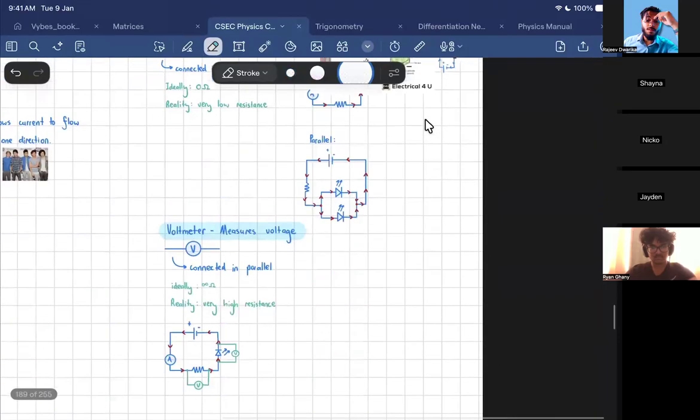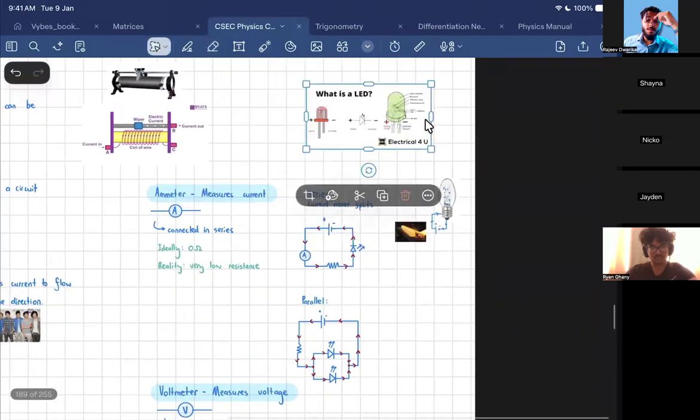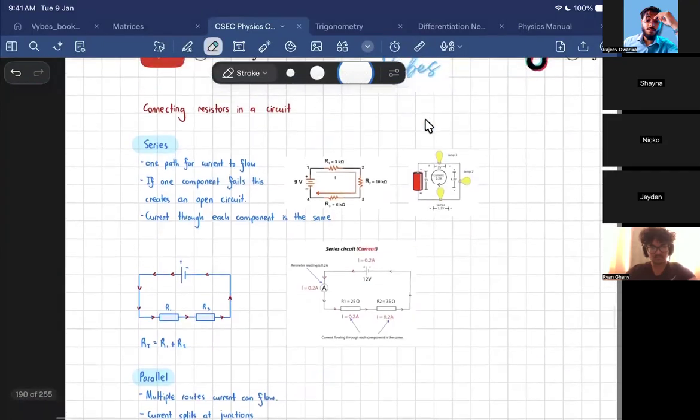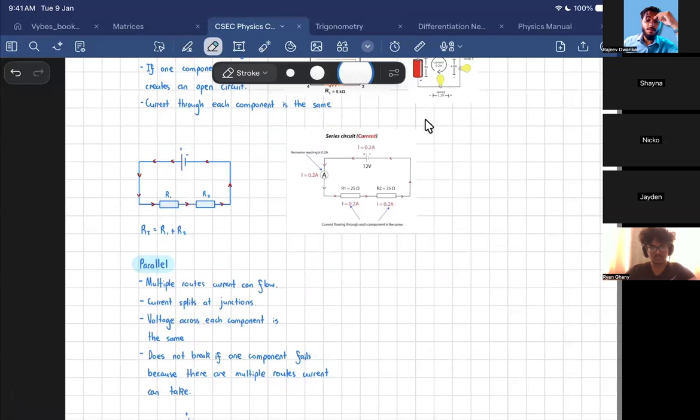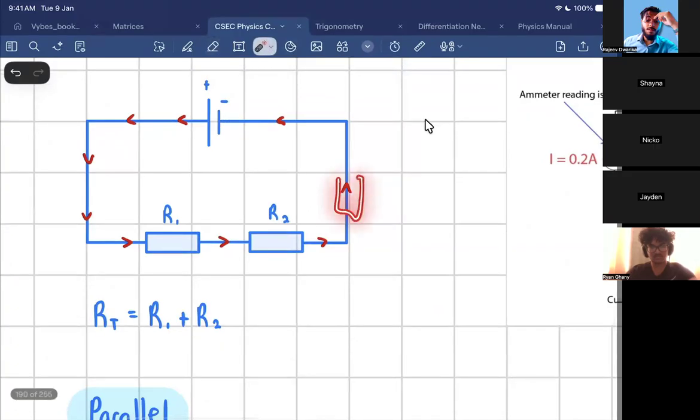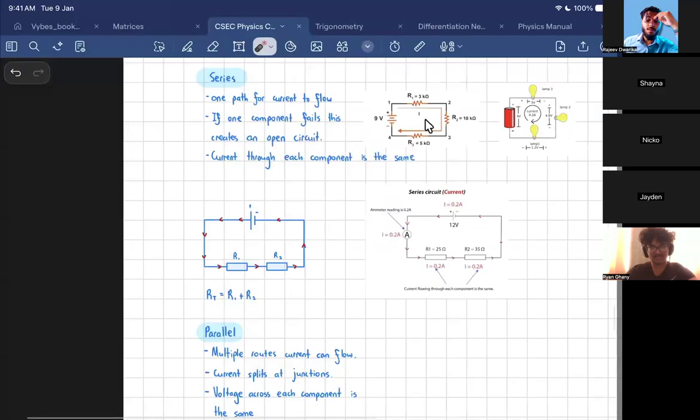Before I move on, you need to know how to combine resistors in series. It's really simple. Ryan, if you want to combine resistors that are in series, you literally just add them. That's all you're going to do. R1 plus R2. Doesn't get easier. If you had a third one, what do you think you'd do, Ryan? Add that one too. That's literally it.